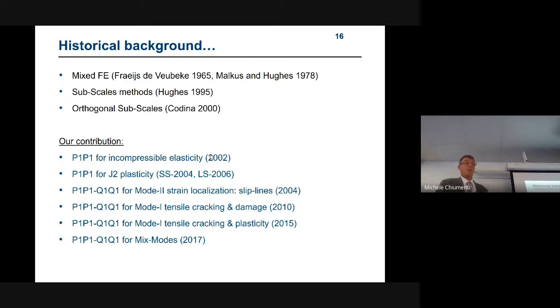So at the end of the day, for instance, if you want to use a displacement pressure solution, because it allows you to solve elastoplasticity problems, you should work with quadratic field in the displacements, quadratic element for the displacement, and linear element for the pressure. This is expensive and has some other problems, but should work. It works. But if you want to use a cheaper element where you use linear displacement and linear pressure, this is incompatible. And so you need to do something else.